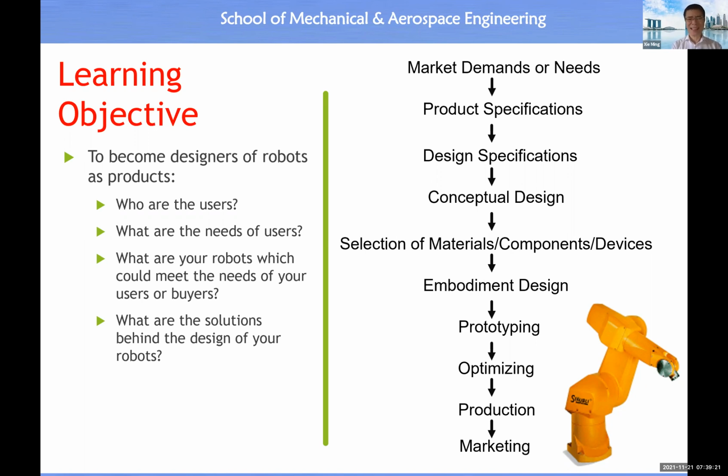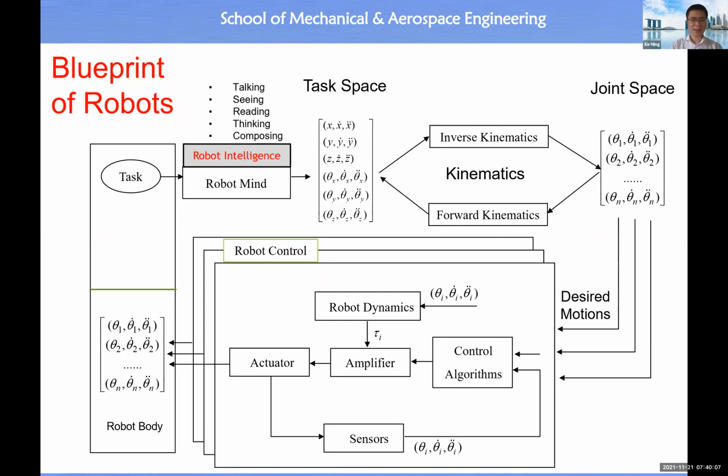And from the study of module 1, you understand motion could be described by the equation of a trajectory of some important motion coordinates, such as X, Y, Z, and theta. For a mobile base, the two important motion coordinates will be the circular velocity of the left wheel and the circular velocity of the right wheel. All right. Therefore, your focus should be on the answer to question 3 and question 4. And this slide gives you the general answer to question number 3.